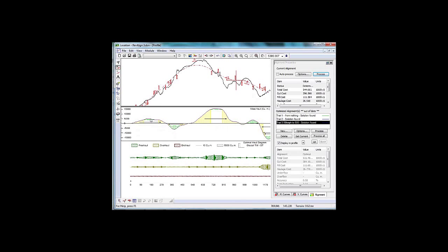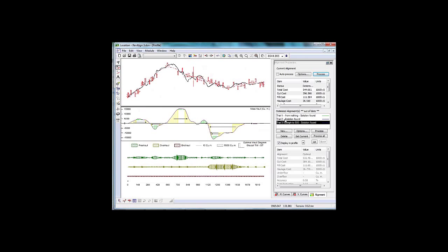So this is the mass haul diagram just underneath the profile, and then here we have the actual haul of material glacial till, and as you can see, it actually matches the mass haul pretty closely. But the first thing to notice is that it is actually, now why am I not getting the full thing? There it is. There's the full thing. It's matching it pretty closely, but this is just the glacial till. Then there's also the solid rock that's being cut and filled as well.